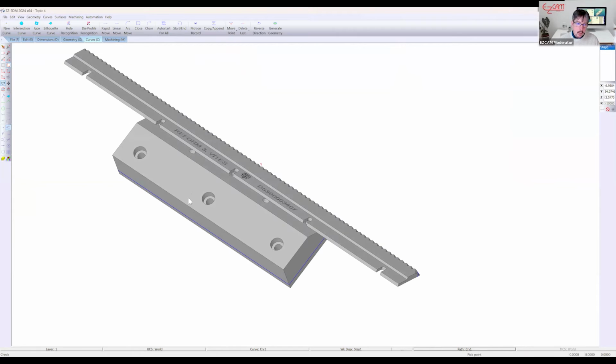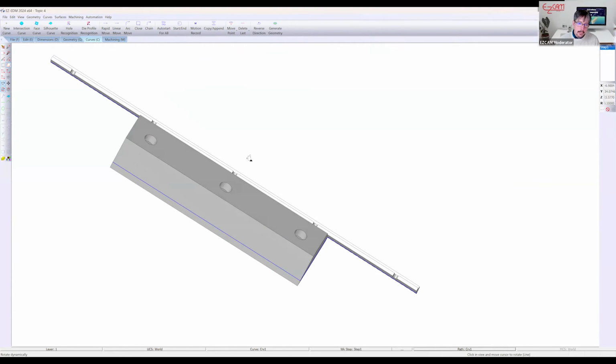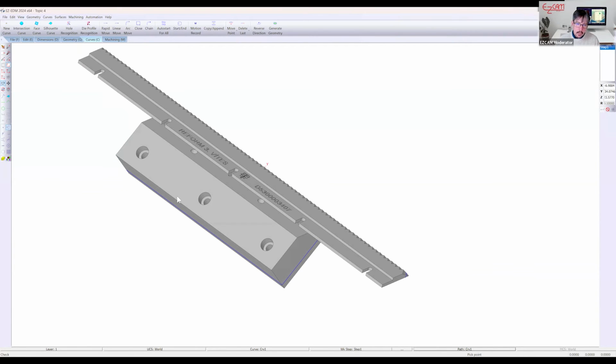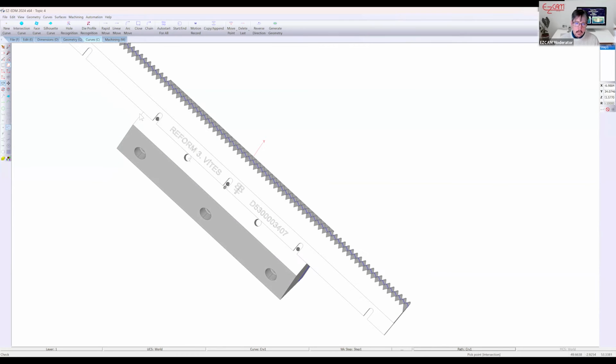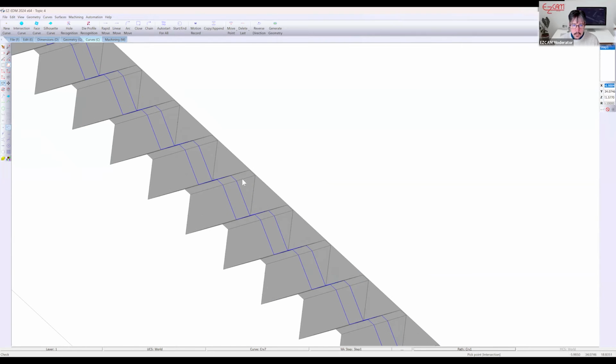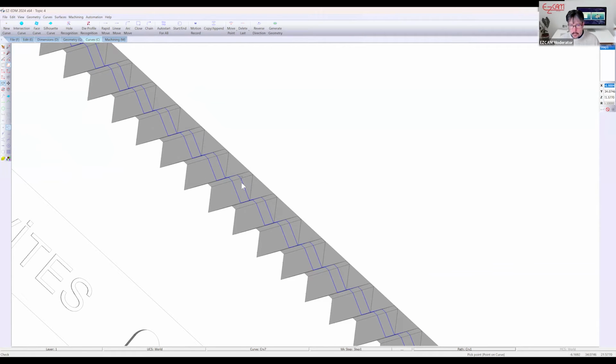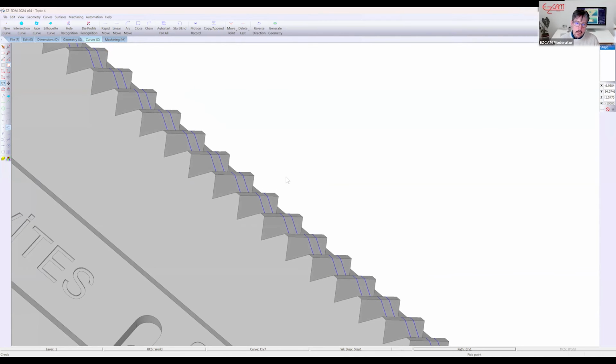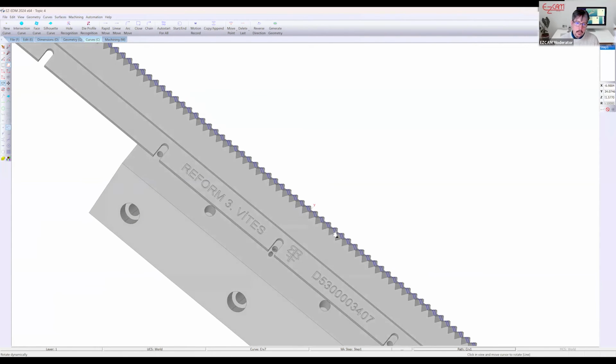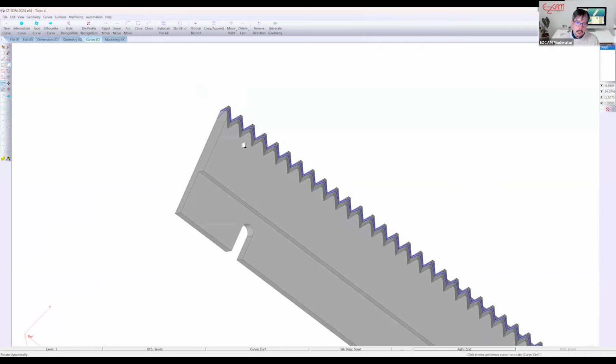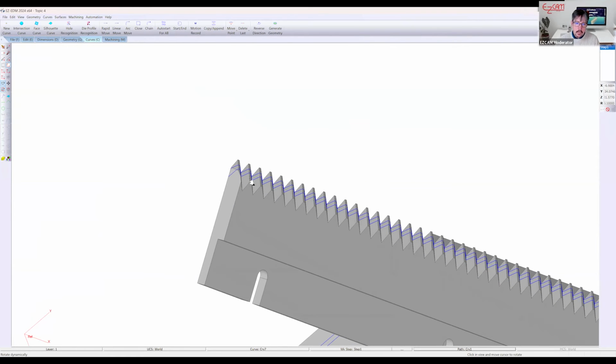And if we look at that curve, you can see it sliced the model at that level, giving us a little bit more of a curve than we wanted. So now I'm going to use that command again. I'm just going to adjust the Z height to 21. Now we get a second path. Now for 4-axis, you don't have to be on top and bottom. You can see that we're going to use these two curves to give us what we're after. But now we have to contend with that curve that's been sliced, the extra.